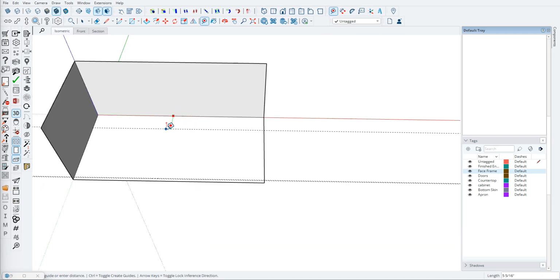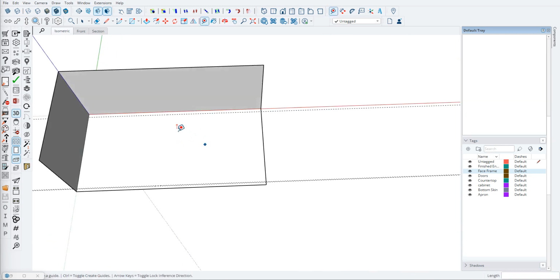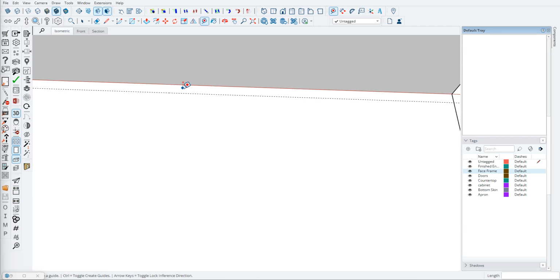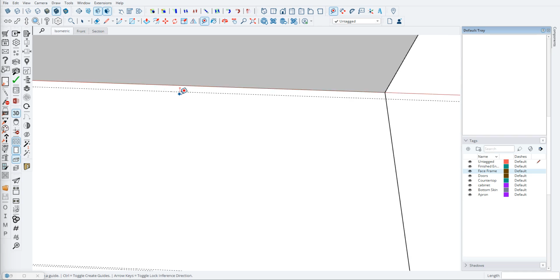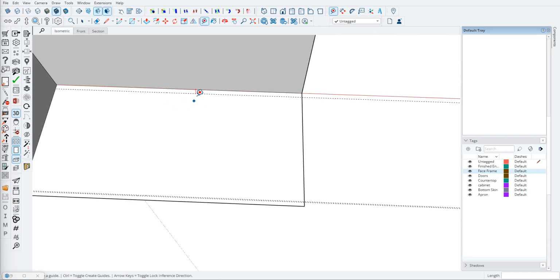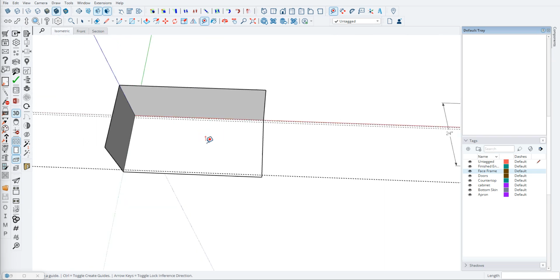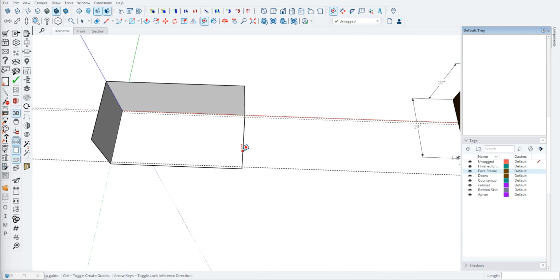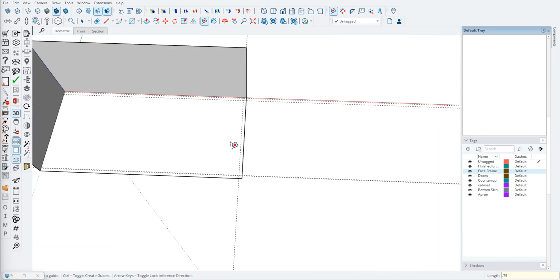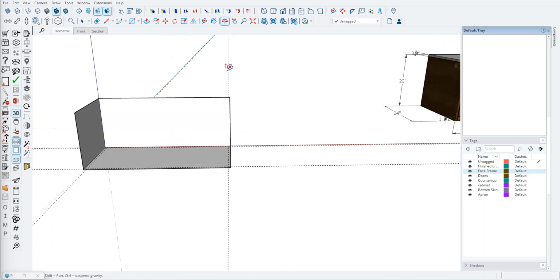On the back, how we build cabinets, we always go 1 inch from the wall to the interior of the cabinet, and we either use a 3/4 back, 1/2 inch back, or quarter inch back, and whichever one of those three we use, we offset the rest of the inch, which we call a nailer. So in this case, it's going to be a 3/4 back, so we're going to draw that back in right there, and that leaves a 1/4 inch nailer that's going to hit the wall. The finished ends are 3/4 of an inch thick, so I'm going to hit 3/4 there and 3/4 there.